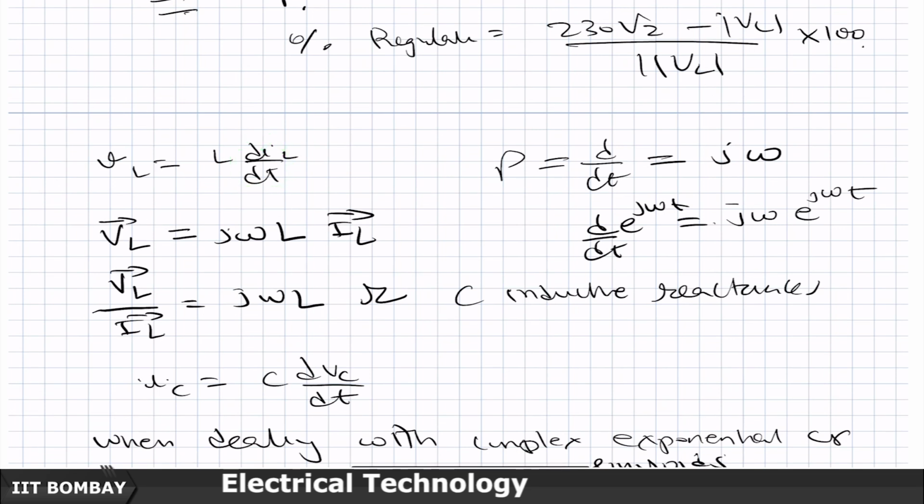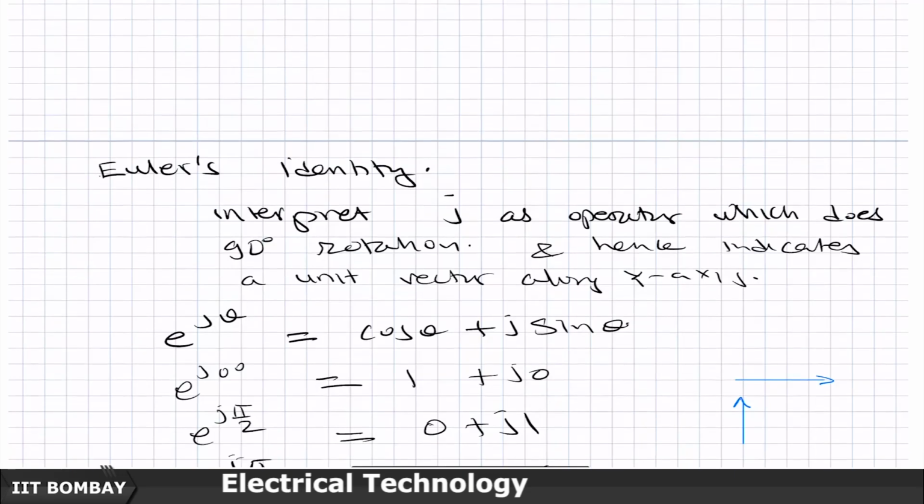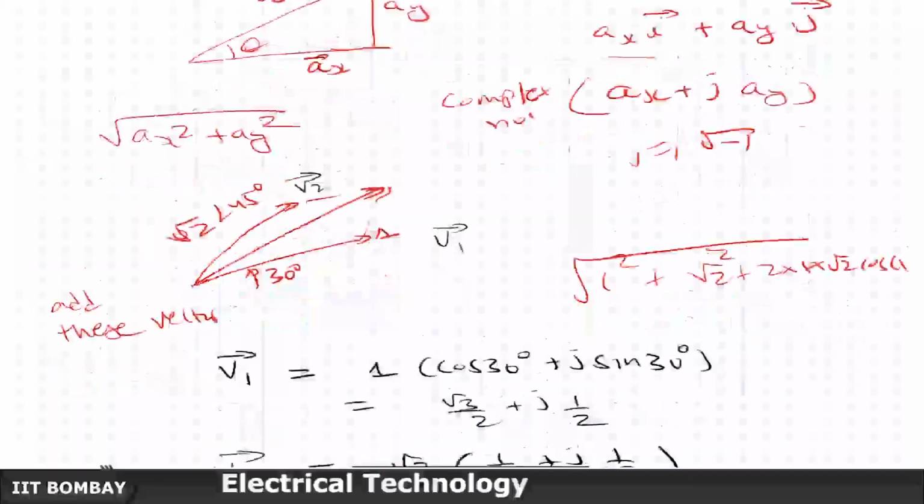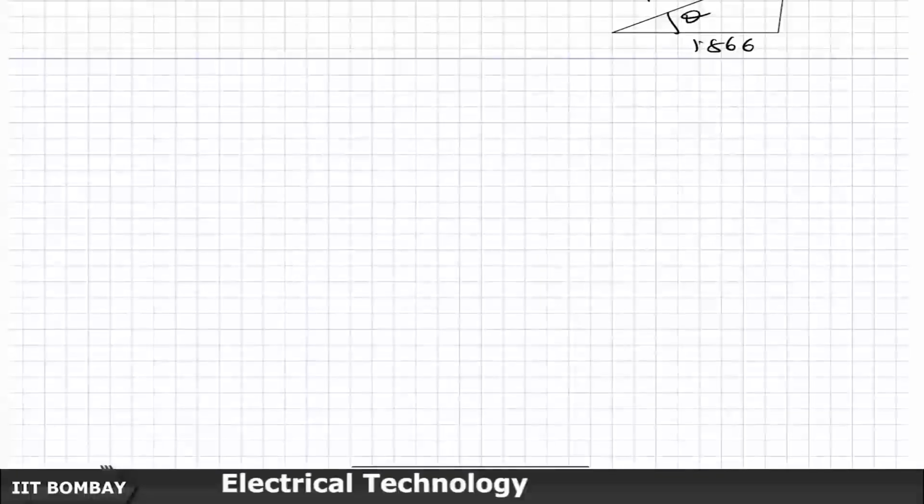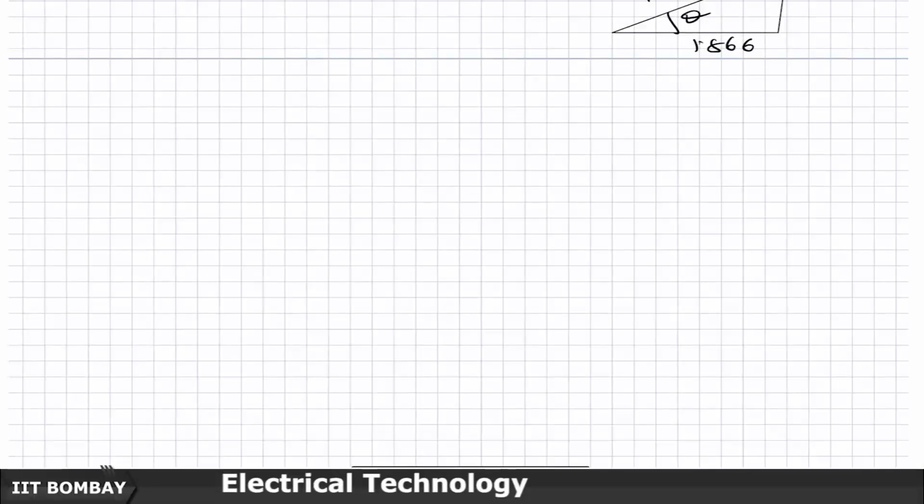Complex numbers allow us to play with first order differential equations with ease. So, both vectors and differential equations, these are the two things which we have to bother about when we are solving our circuits. Both of them are neatly handled through complex numbers, and therefore, you would find that all phasor analysis in electrical engineering is done using complex numbers.